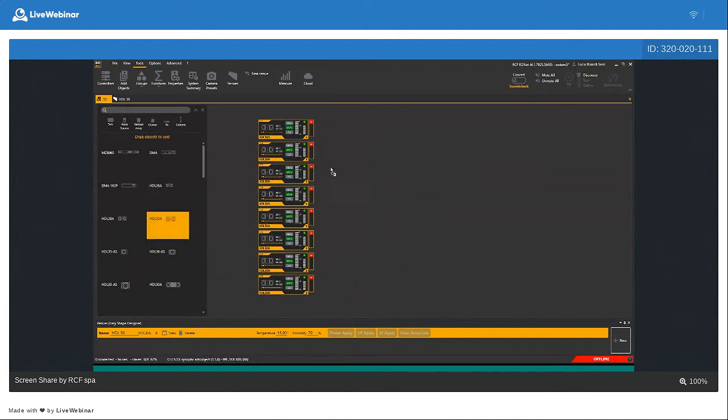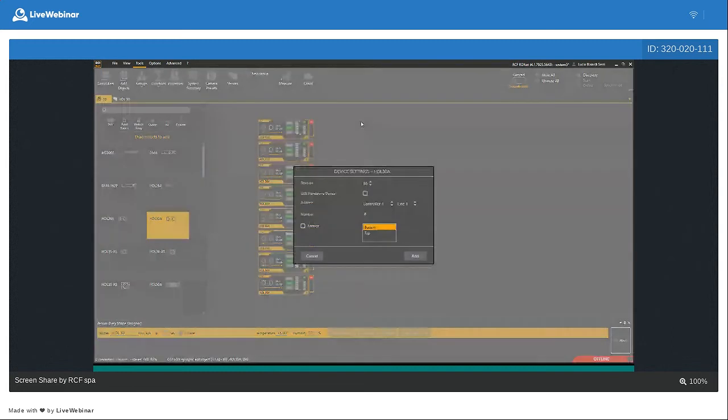So drag again on the workspace the icon of the HDL30. We have 8 boxes, but at this moment the boxes will be connected to line 2 of the control 8. It's more convenient to use another line instead of making a round with the network cable, because we could use just one line, since in each line we can connect up to 32 devices, but it is not convenient.